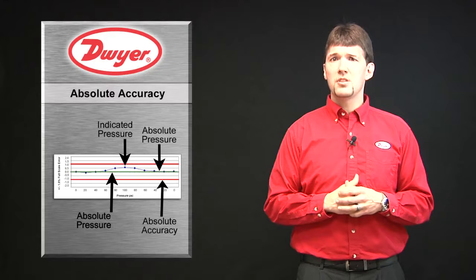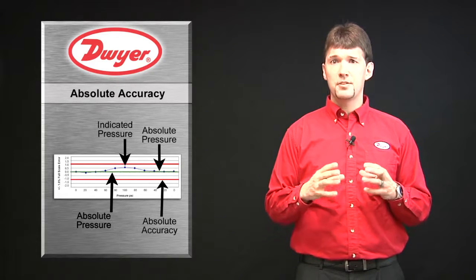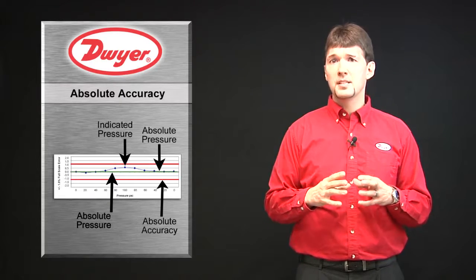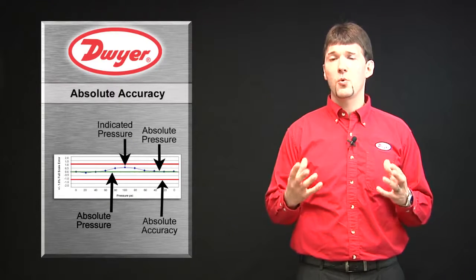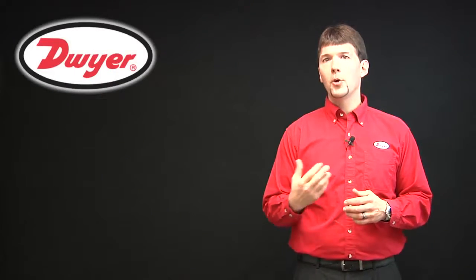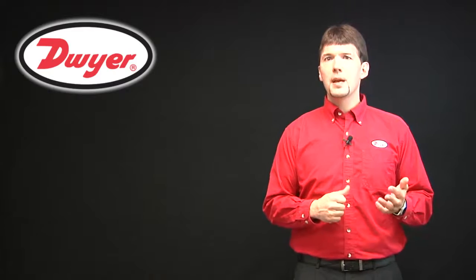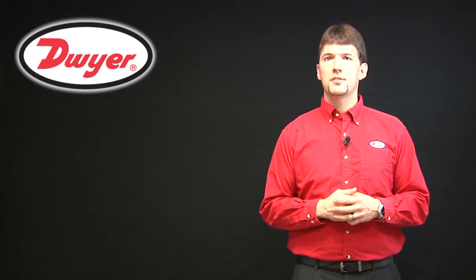For those sensors that use equations to formulate the accuracy, it's much more difficult to validate if the pressure sensor accuracy is correct because it can vary widely based on which equation was used to calculate its accuracy. I hope this video has given you a better understanding of pressure sensor accuracy and will help you make a more informed decision when selecting pressure sensors in the future.